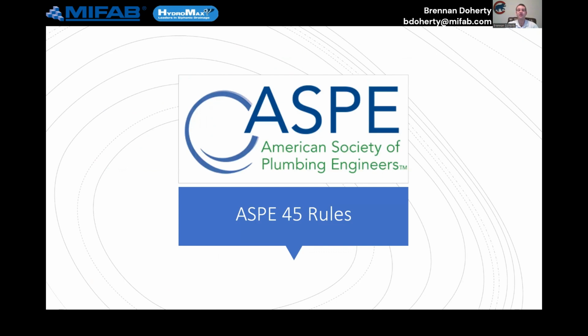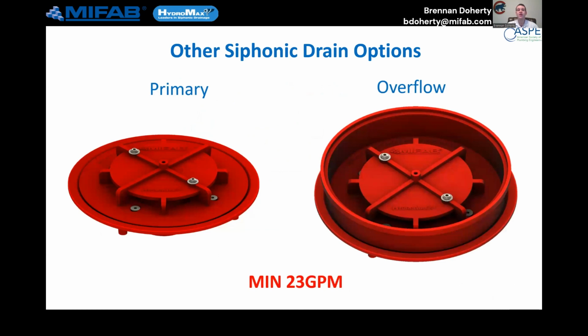ASPE 45, what we want to be aware of if we're looking at a project. Number one, we still have to have an overflow by code. Just because your primary is that much more efficient doesn't mean you get away from an overflow. Your overflow does not have to be siphonic just because your primary was. It can still be gravity. It can still be scupper. If it is siphonic, we're going to start with a 2-inch water dam standard, the same as we're doing with gravity, no different.